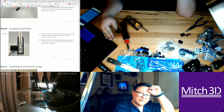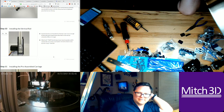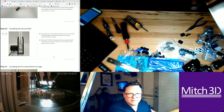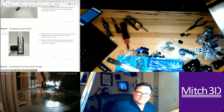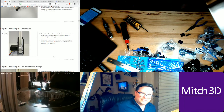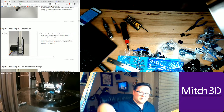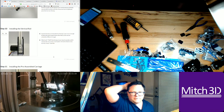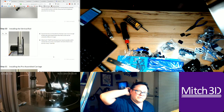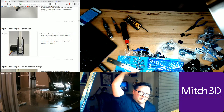Like the last time the spool was basically at my butt, and a lot of the weight on this is going to be lower back weight, so the batteries are going to be mounted near the lower back, and the weight of the motors, which are the heaviest part, and the extruder is all going to be on the base of this printer. So the weight distribution will be all low center of gravity, and then the height is really just up here.